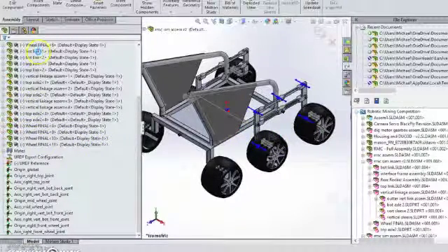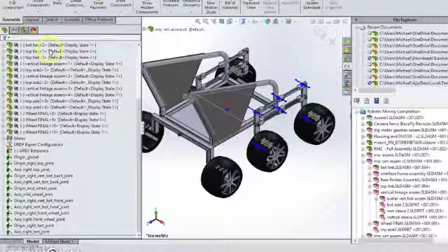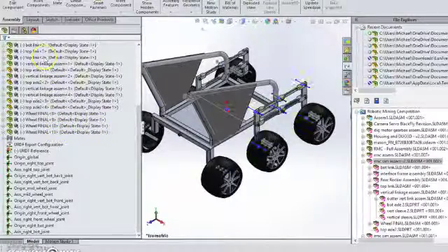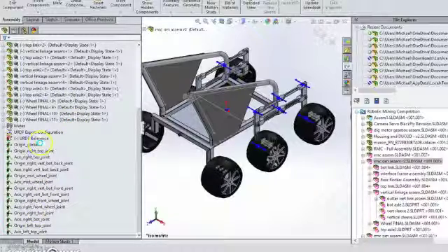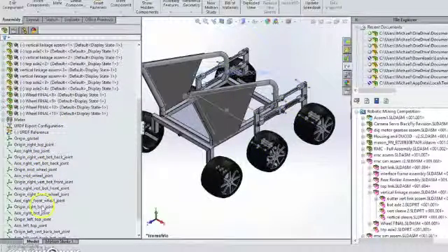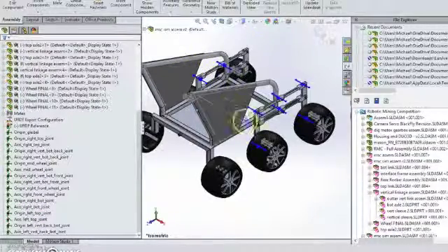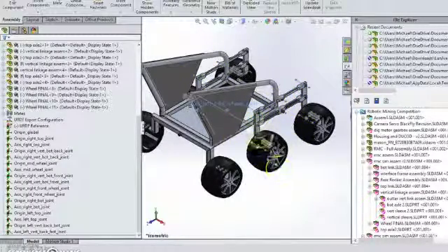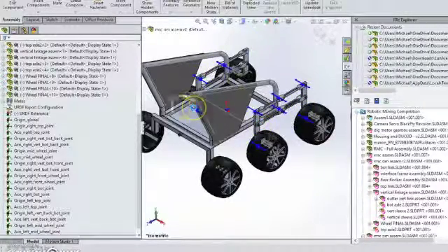So when you're doing this, you can kind of watch your assembly here to see if something gets fixed. If you see something gets fixed, that's usually a sign that the assembly can't solve the URDF structure as you've currently constructed your assembly. So here we see it's constructing the origins and axes for the joints, and it's all the way to the left side now. It's completed the series of open chains on the right side, so we go from the top all the way down to the wheel, and then the bottom. And now it's done a similar thing on the left.